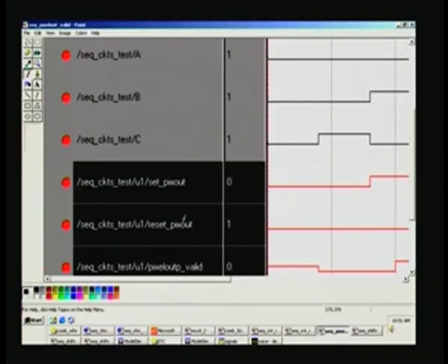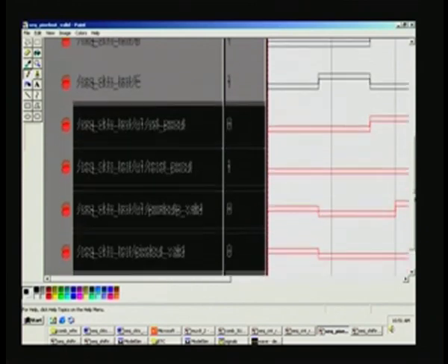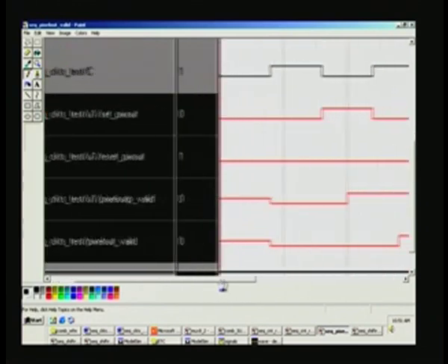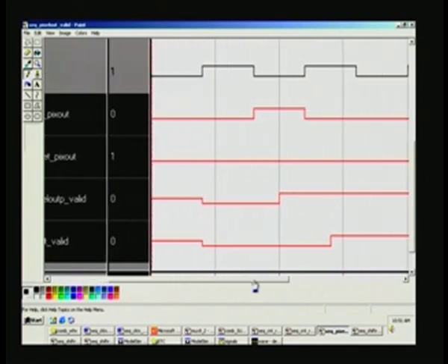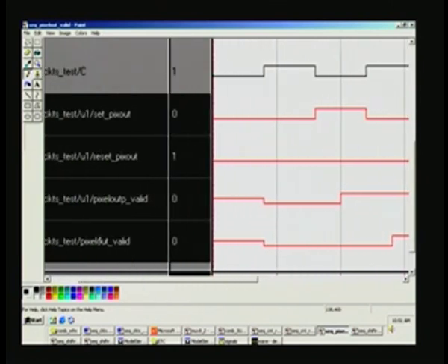And what remains to be done in this is pixel out P and pixel out valid, right. Notice that I said pixel out valid is precisely the same output as this, and the only difference is this will happen 1 clock pulse later on, because that is the time I want to pick it up and output saying that the pixel is valid right at this point of time.